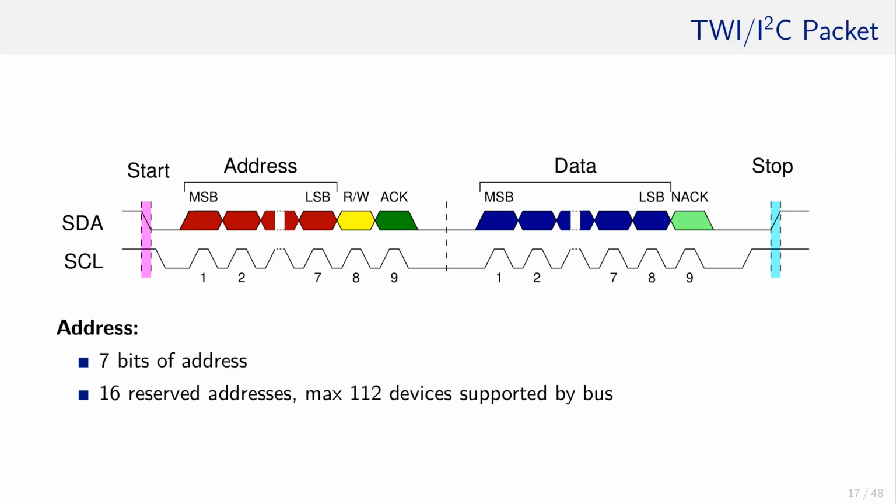The addresses of the slaves are usually fixed and can be found in the datasheet of the device. In many cases, it is also possible to choose from, for instance, 3 addresses so that a developer can use 3 EEPROMs on the same bus without address conflicts.